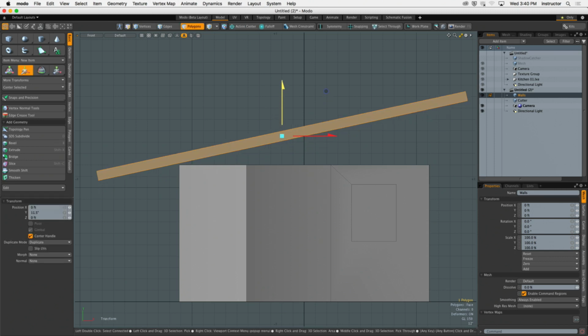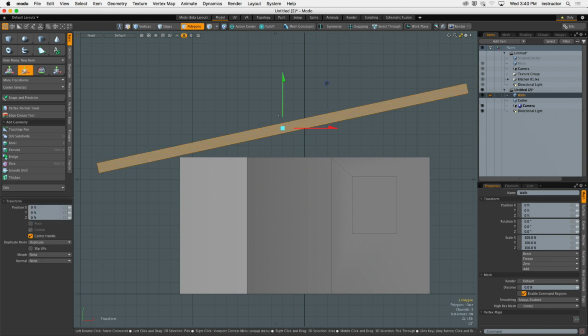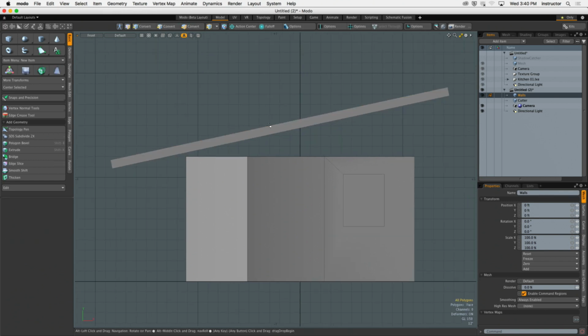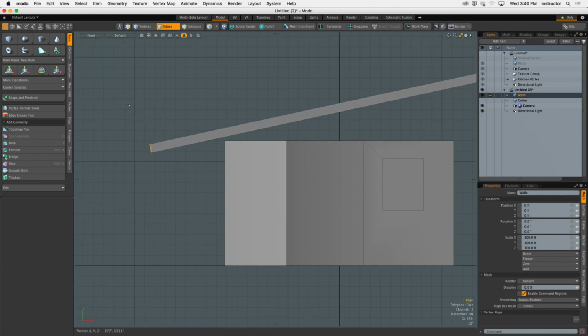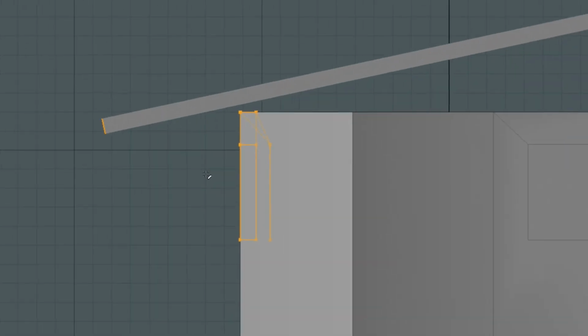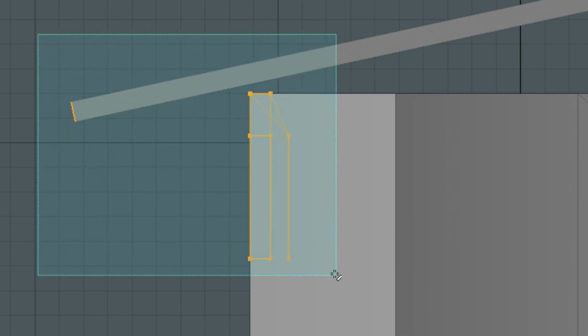So I'm only doing half of the roof. Something like that. There we go. I'm liking that. That's looking pretty good, okay? This is half of the roof, okay? What I don't like is this. Look at the overhang way over here. Roofs don't have that kind of overhang. The eaves of your roof, they're not that big. There's a little bit of an overhang outside, over your walls, but not that big. That's like this long of an overhang. It should be probably about like that, 18 to 24 inches.